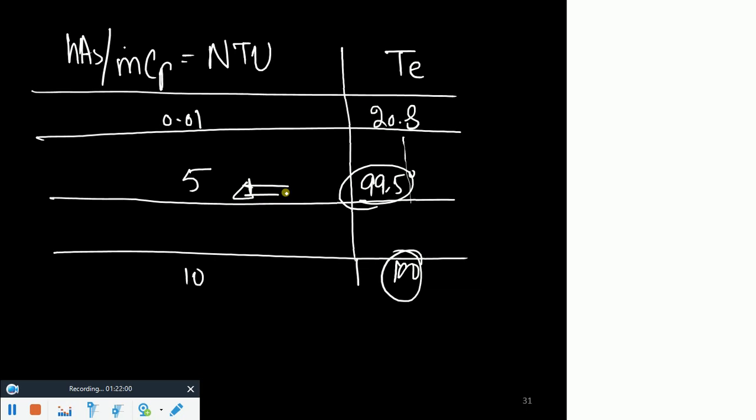So this is the point, that you need to be very careful about NTU, and whenever you have a constant surface temperature condition, you should be looking at NTU value very carefully, and you should be using what? Logarithmic mean temperature difference. Okay.